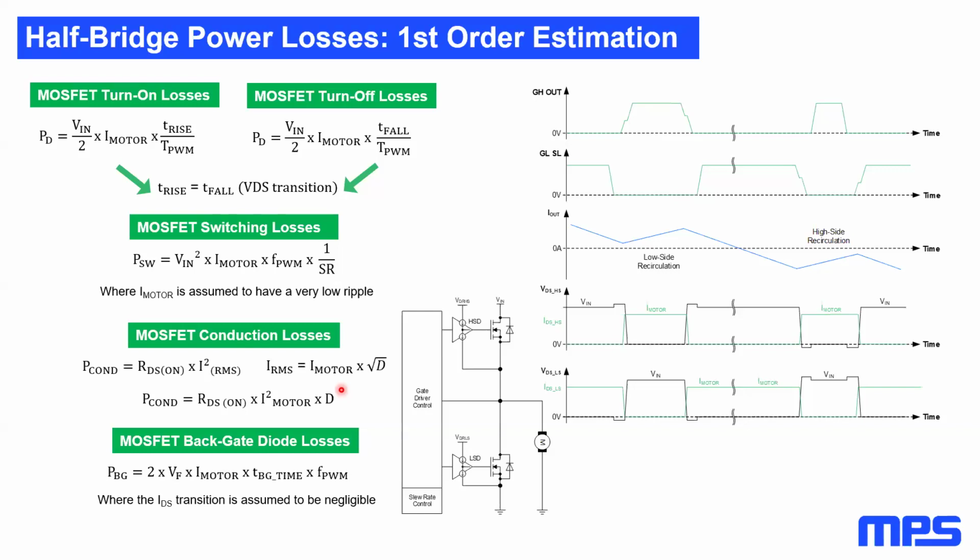As conduction losses, they can be calculated using RMS currents, and you have to know the waveform of current that flows in your DC link capacitor. So how much you have filtered before that matters.